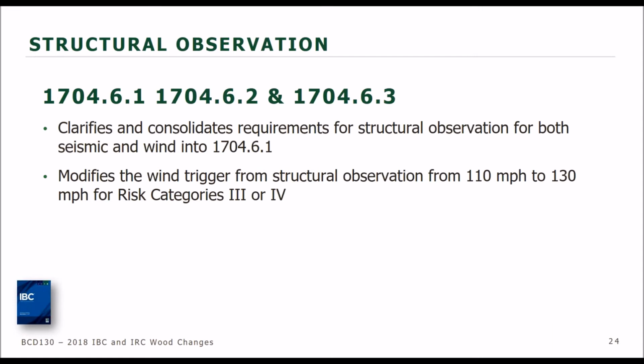And for structural observations, now we're into chapter 17, which actually is titled Special Inspections and Tests that include structural observations. And what we see here now is there's a general section, 1704.6, that covers structural observation in general. And we see some clarifications in the 2018 code where they've clarified and consolidated what was common to both seismic and wind structural observations and tucked it under the structural observations general section. So that was a clarification and a consolidation.